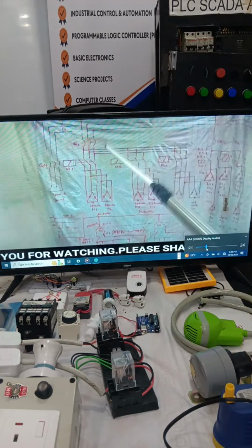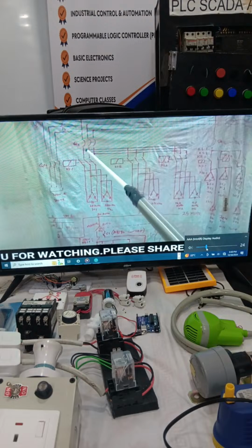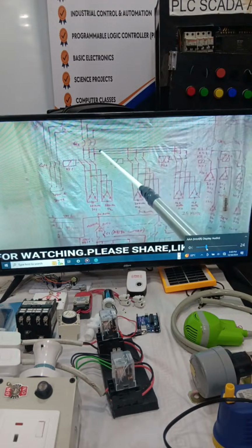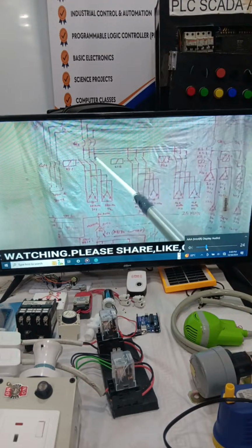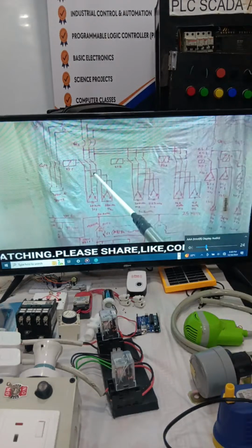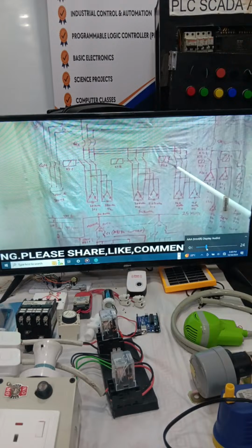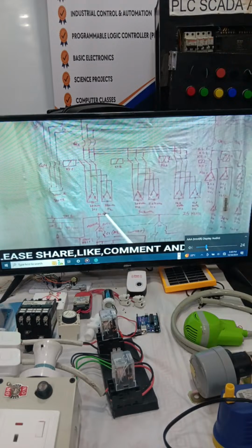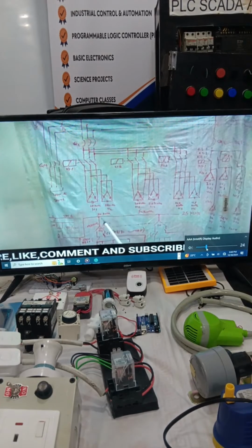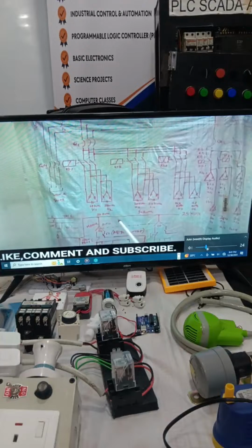Then from the bus bar there will be one branch breaker Q1. Q1 will feed three sets of contactors K1.1, K1.2, K1.3. Again each contactor will feed two capacitor banks parallel to each other. Here it is 25 kVAR, 25 kVAR, total 50 kVAR. Designation is 1C1 and 1C2.